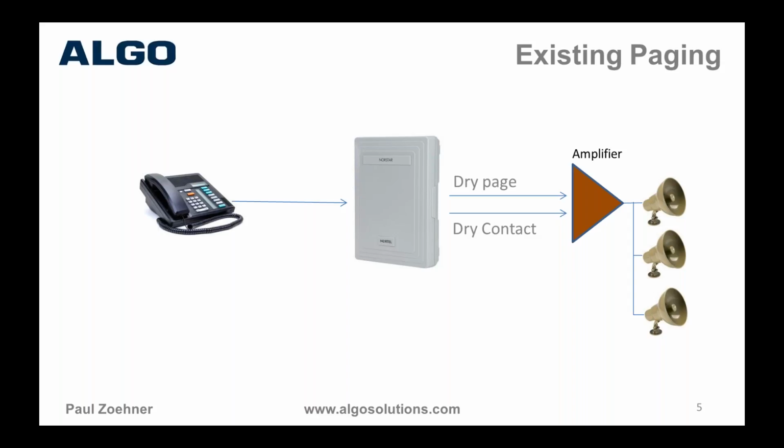I don't know if this slide means anything to the people listening this morning, but Nortel Networks had made a phone system called Northstar. BCM followed that, probably one of the most popular phone systems in the world at the time. I still have one in my home. There's a lot of them out there. And the way that worked for paging was you had a dry page port, a dry audio, meaning no DC on the wire pair, and a dry contact to either mute the music or activate the amplifier.